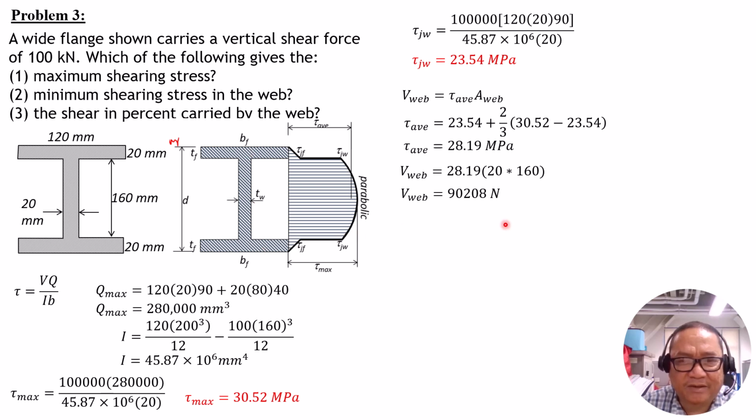So I hope that you notice that in your subject steel design, the shear area is the thickness of the web times the overall depth, because this is almost 100% of the shear carried by the section. So that's why in steel design, the shear carried by the flanges may be neglected, because this is almost the same as if we substitute D instead, not the web. We include this vertical shear, this shear area here.